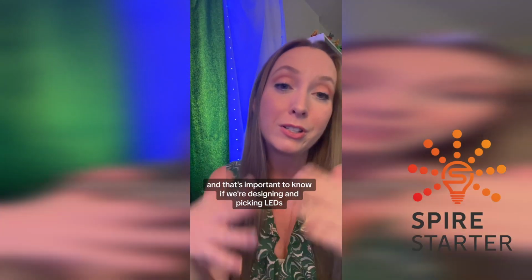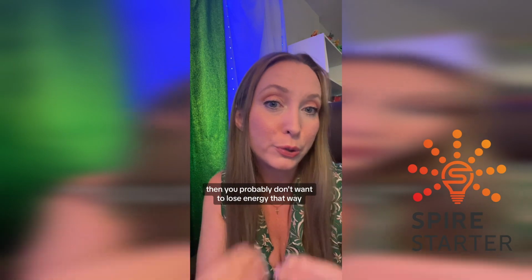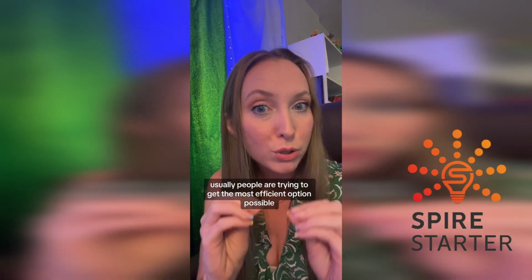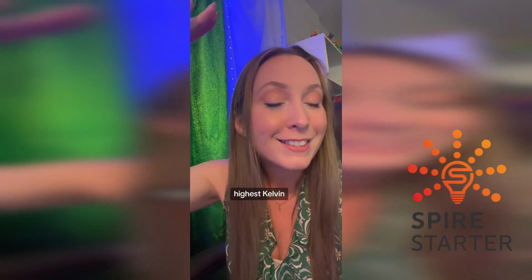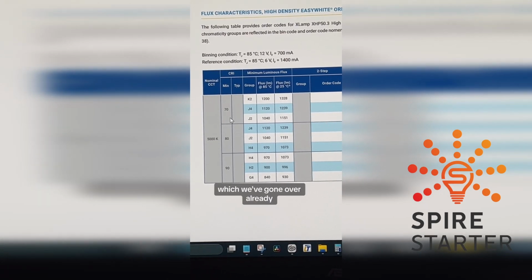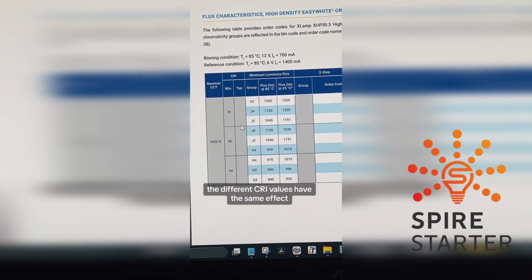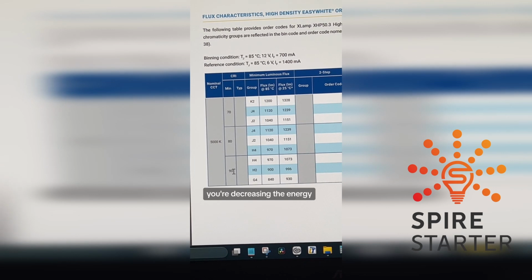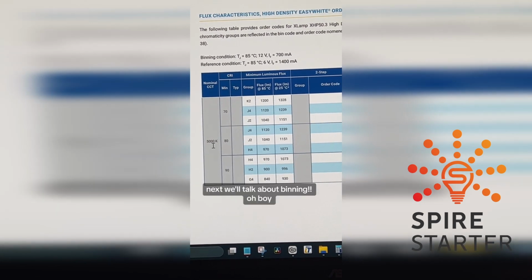And that's important to know for designing and picking LEDs, because if you don't actually need that warmer color temperature, then you probably don't want to lose energy that way. Usually people are trying to get the most efficient option possible, and that's to go the bluest white possible, or the highest Kelvin. On the next column, we see CRI, which we've gone over already: 70, 80, or 90, with 90 being the best one that they offer here. The different CRI values have the same effect as going to a warmer color temperature. When you're increasing the CRI, the color rendering index, you're decreasing the energy. So this 90 CRI is going to have lower lumen output than the 70 CRI. Next, we'll talk about binning.